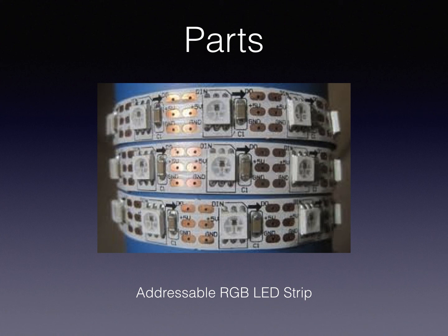If you include and download a library in your Arduino code, you can set up one of these strips and write RGB values to individual LEDs just as if they were part of an array. So I knew that this would be very simple to accomplish what I needed to do for my project. I picked up one strip, which is a meter long and has 60 LEDs, so they're fairly closely spaced together. They're less than an inch apart each, and so I knew that they would work really well for what I needed to do.